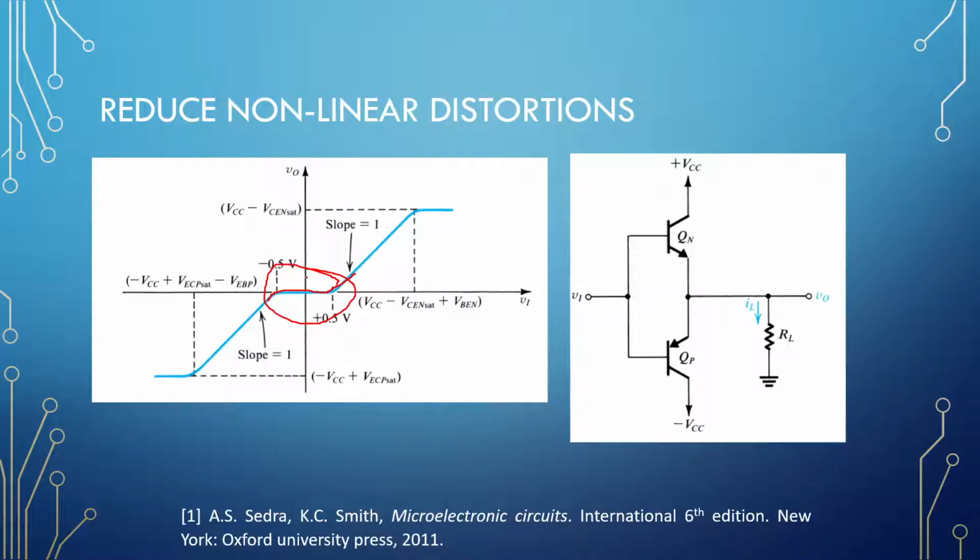Okay, so this crossover distortion, this 0.5 volts, is divided by the gain of the operational amplifier and thus decreased. So that is one of the properties of negative feedback where you can clearly see it, and I've done this in my video on class B amplifiers.